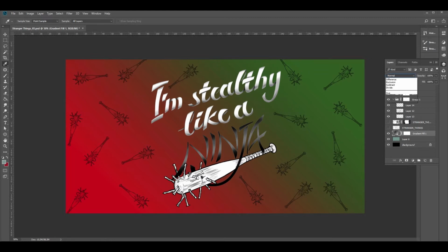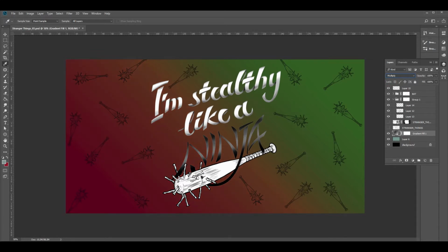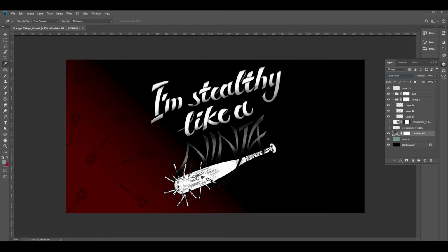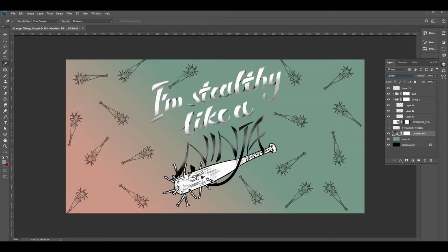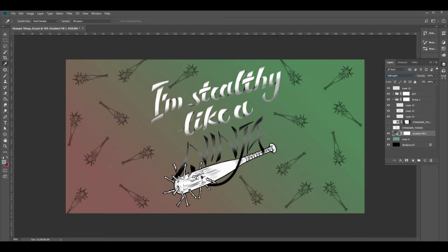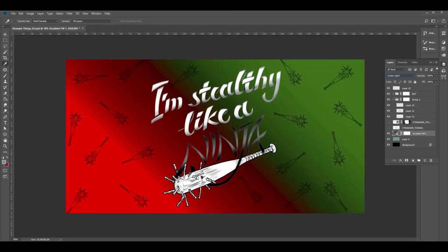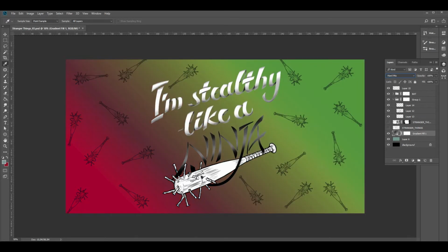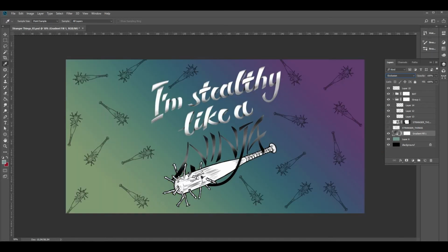As you can see, the gradient I have selected goes from red to green when blending mode is placed on normal. But if we use the other options in the blending mode, something different will happen. Particularly, the one we are looking for is difference, and as what it makes is convert colors to their opposite, guess what? We'll get pink to turquoise transition. Right what we needed.